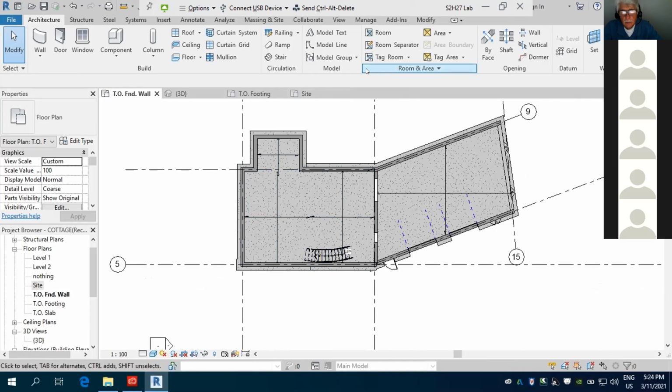I'll tell you what my concern is, Brandon. My concern is that you might have a partition here on the ground floor, which corresponds to the partition that you see on the second floor. And there's a good chance that you have a column hidden in that wall that corresponds to a column going onto the second floor that's supporting the beam on the roof, and therefore the whole load from the roof.